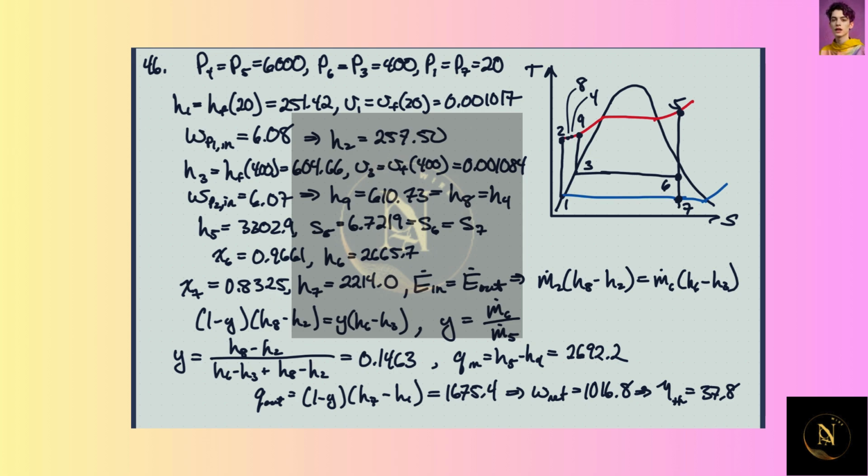we come up here. From the pump, we pump it up. Again, we're at 6 megapascals at the high side. At this bleed pressure, we have 400 kilopascals, and down here at the low side, in the condenser pressure, we have 20 kilopascals. So we bleed some off here, and then we basically pump it up to this pressure here. We have this pumped up to that pressure also.